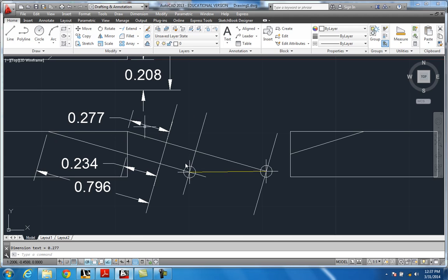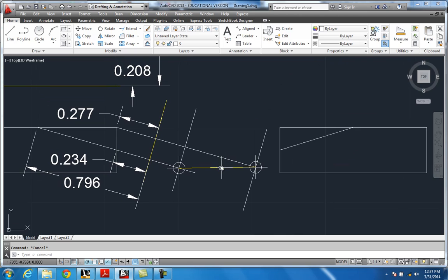So all you have to do is, this is going to be our fold plane line right here. And of course this right here was our fold plane. I'll change it to yellow just so it'll keep everything consistent. And this was our fold plane. We'll make it yellow. Now I want to fold this. I'm looking at this in the edge view. I want to fold it up so I can see this thing in its true size and shape. And basically all you have to do is just offset these numbers.